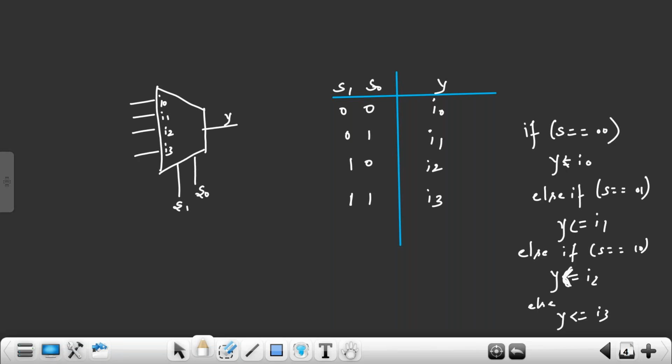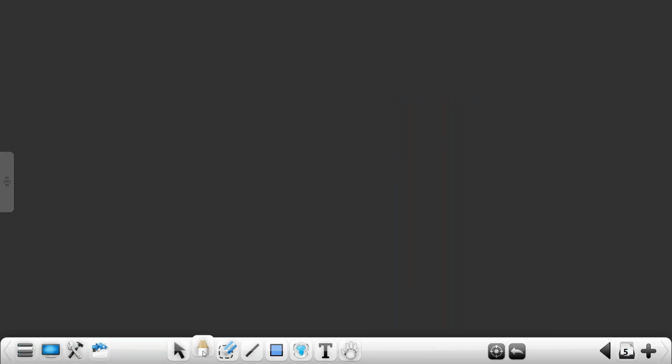So Verilog or VHDL uses if statements, case statements, and procedural blocks to describe a circuit in the form of behavior, how the circuit behaves, not in the form of structure. Structure means gate level implementation. If it is a bigger program, generally we will not implement it like this. For example, I have a bigger design. How is behavior captured?